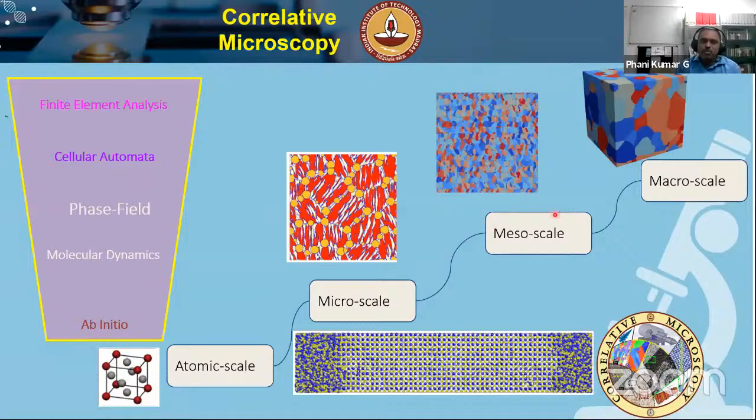And then we come down to mesoscale, where you have the information at the level of tens of microns, and that is where the metallurgists are fascinated by the microstructural information there. And we can go further down to microscale. We have further information, phase information, the segregation aspects, etc., and also the atomic arrangements, and all the way down to atomic scale, where the individual atoms and their interactions with the electronic cloud that is surrounding them play a role in the defect formation at that scale.